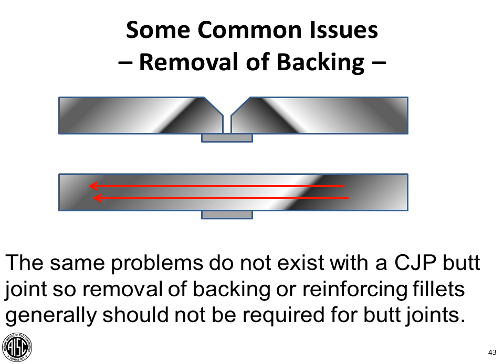and that they're highlighted in some way, because whether we're talking about a seismic project or a non-seismic project, one of the issues we do sometimes run across is where there may be a requirement in the contract documents, but maybe it got buried somewhere and nobody really picked up on it until late in the project, and it can cause some problems. So the fabricator may have missed it on the front end. The engineer of record may have missed it in the review of the shop drawings, and now you're well into erection in some cases, and it gets picked up. So it just is to everybody's benefit if you try to highlight anything that's unusual to the best of your ability.